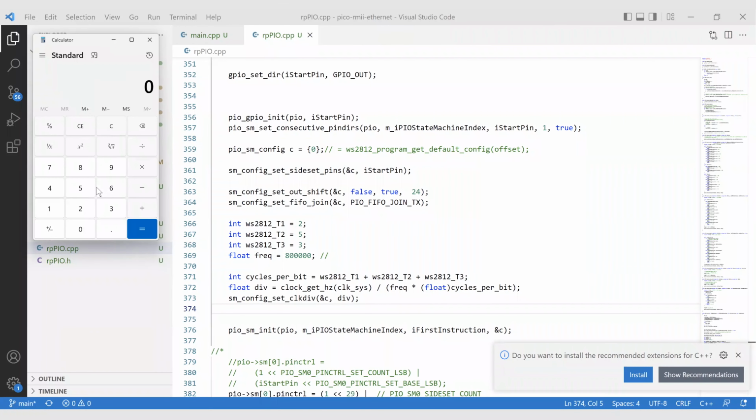Now you need a lot of power. That's one drawback. You definitely power up externally. Each color takes up to 20 milliamps. So we're okay with 4 on this, maybe up to 8. We're powering off the USB here. For 33,333 LEDs, that's about 2,000 amps at max. So you need a Tesla Model S Ludicrous or something.